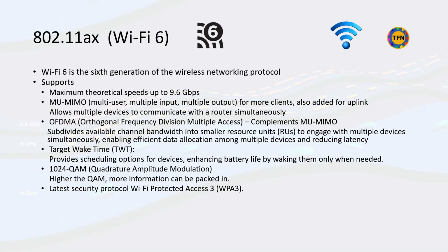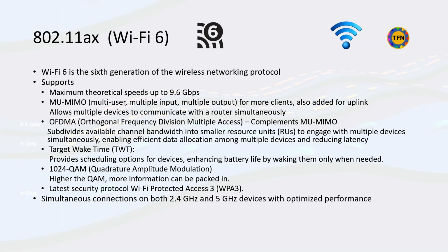OFDMA, or orthogonal frequency division multiple access, complements MU-MIMO by subdividing available channel bandwidth into smaller resource units to engage with multiple devices simultaneously, enabling efficient data allocation among multiple devices and reducing latency. Wi-Fi 6 supports target wake time, which enhances battery life by waking devices only when needed. Wi-Fi 6 supports the latest security protocol, Wi-Fi Protected Access 3 or WPA3, designed to safeguard Wi-Fi traffic. Wi-Fi 6E is an extension of Wi-Fi 6 with 6 GHz band.